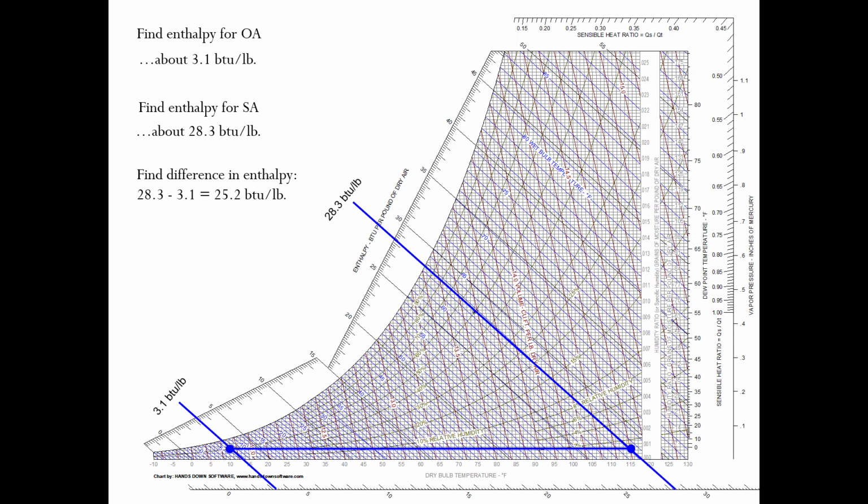So pretty straightforward. The enthalpy scale is on the outside of both axes, and all you have to do is take a ruler or straight edge and line up the enthalpy scales on both sides so that they go through the same numbers and match up while they go through the point that we've plotted for our airstream.